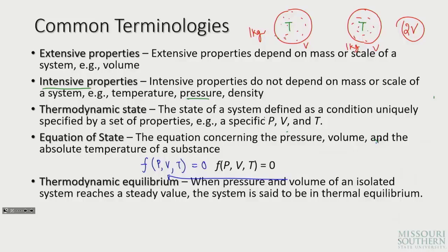Now let's talk about thermodynamic equilibrium. It's a very, very important concept. If an isolated system is left to itself, the pressure and temperature at a given point approach a steady value with the passage of time. When these quantities have attained a steady value, the system is said to be in a state of thermodynamic equilibrium. In such a system, the temperature, pressure and other thermodynamic variables of a homogeneous system are the same at all the points.